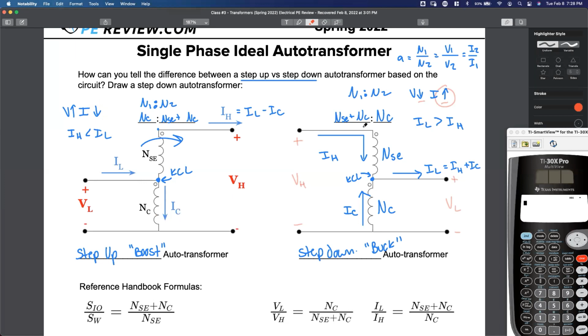Over here on the right, is this voltage step up or step down? We know our voltage is stepping down, so our current is going up. So is our common current. Neat, huh? That's just a coincidence, but it's an easier way to remember it. Light bulb, says Tyler. Cool trick, says Cyan. Yeah, easy. It's the little things you figure out after doing hundreds and hundreds of practice problems that really increase how fast you can solve these problems.